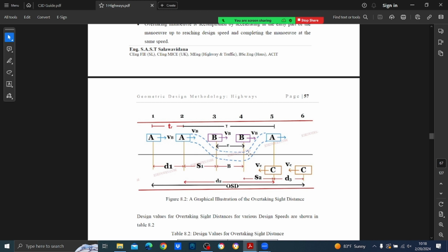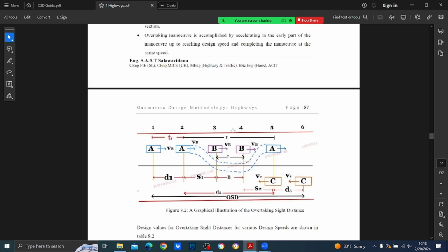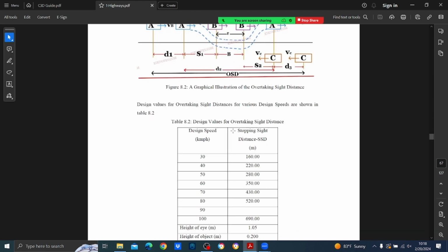If there is side distance, they give the dash line. If there is no side distance, they decide on the double line or the single line. It is better to provide overtaking side distance as far as possible, but stopping side distance should be everywhere, otherwise it is dangerous.